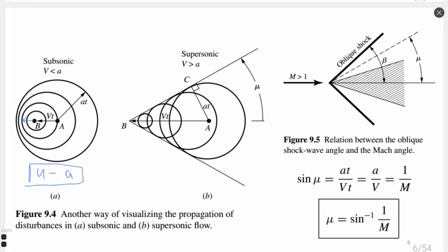And also Anderson introduces a relation between velocity and speed of sound that is called the Mach angle. Here we denote the Mach angle as mu, and geometrically it can be calculated when we analyze the relation between speed of sound and velocity of movement. And this Mach angle, which shows us the angle at which disturbances propagate, mu, can be calculated geometrically, as you may see, as a function of Mach number.